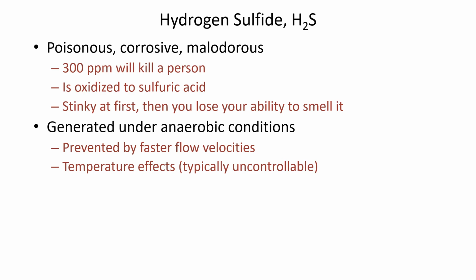But if the pipe is so big that the depth is shallow, then you've got a lot of wetted perimeter and a slow velocity. And slow liquid velocities don't have very much mixing and aeration of the liquid. So there would be a greater risk of hydrogen sulfide forming at the bottom of the pipe as things settle down, causing clogging and collection in the bottom of the pipe. And so one of the risks of having an oversized pipe is that it's not self-cleansing.